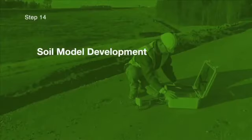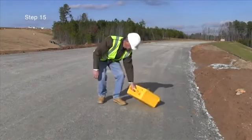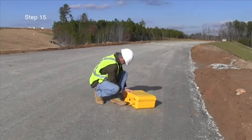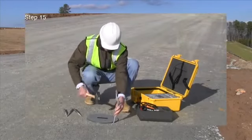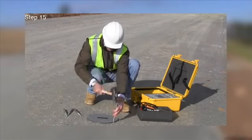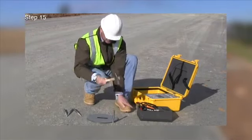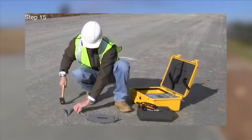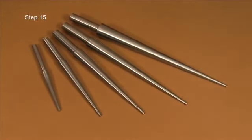You are now ready to proceed with the actual soil model development at your test site. The test site can either be the actual project site you desire to test, or a site that uses the same material that you will be using at your project site. When building a soil model, you should use a dart length that coincides with the expected lift height that you will be using for the project. Darts are available in 4, 6, 8, 10, and 12 inches.